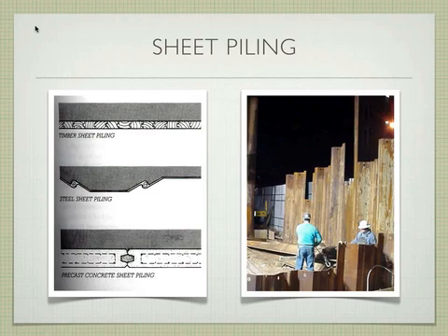Sheet piling can be made of timber, much less common these days. Most commonly it's going to be some kind of metal sheet piling, and it can also be precast concrete pilings that go together. This is the most common, these metal sheet pilings. There's a corrugation of the metal, which you can see here, and a little interlocking joint here and here. So we have this piece that has this little joint there. The same piece flipped around goes this way. You can see it here, we've got the in and the out of each of these pieces. Those pieces slide together and can be rammed in just like those H piles with the wide flanges. You ram them in by tapping them on top. They form a corrugated wall that can then support the soil that you're excavating.